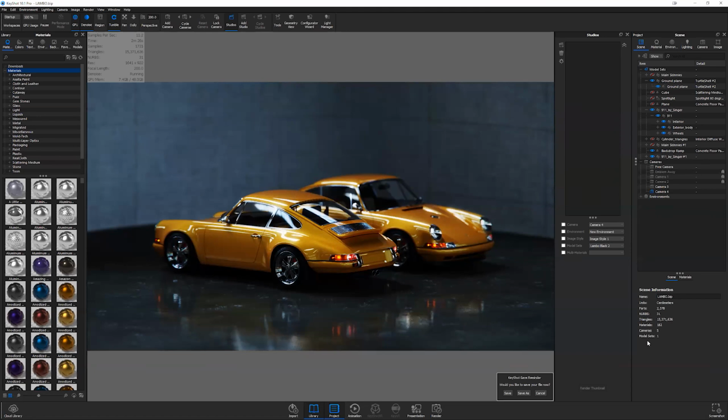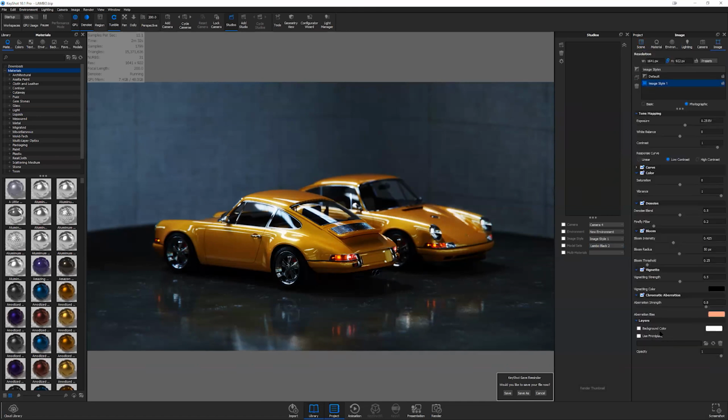Yeah, great question. Thankfully, KeyShot already has the answer. We use a lot of front plates and back plates. So we'll use this front plate tool here, which you'll see in the image bar. We can have our PNG and put this in as a front plate if there's going to be depth in it, if there's going to be something in the foreground or something in the background and our product's going to sit somewhere in between the two. We'll apply that front plate, measure it up, make sure the size is all there, and then even have our background image in there as well. And that way we can composite and superimpose those three images together.